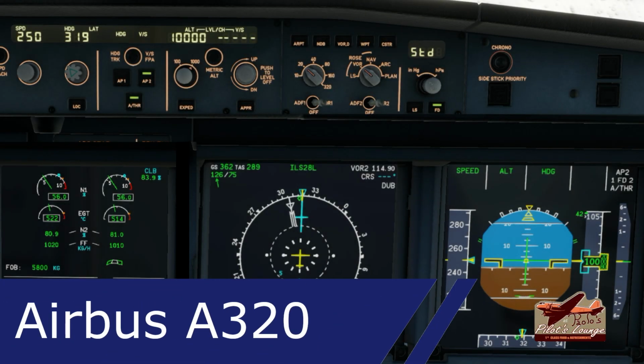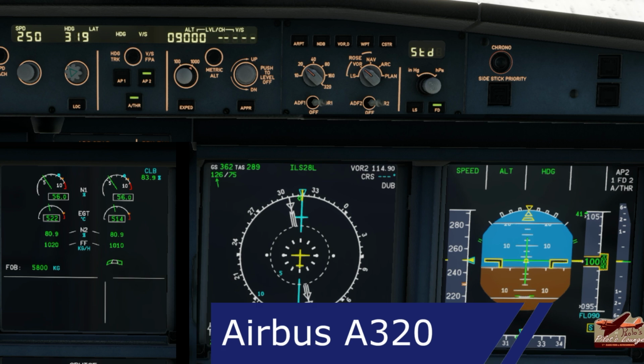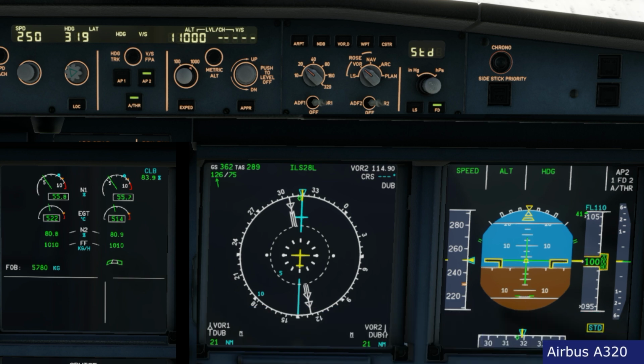In this case, for just a 1000 feet change, I'm going to select, once again, a 1000 feet change. What I could do is rather select a vertical speed, so maybe 1000 feet per minute. So 1000 feet per minute, this time, sorry, if I don't pull, there we go. You see I've pulled, meaning that I've selected VS 1000 as shown on the FMA.